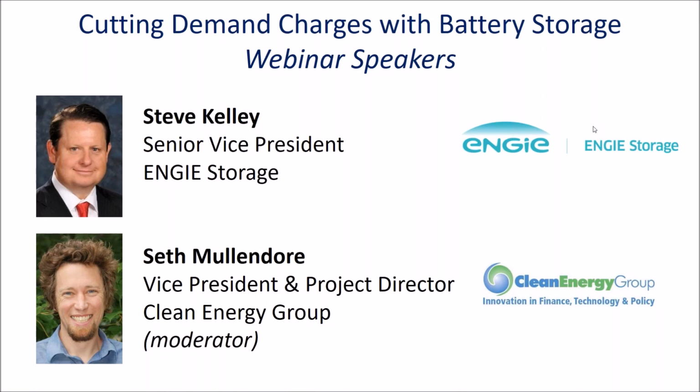Yeah, I think you'll see as jurisdictions and code catches up with technology, they are trying to figure out how to make this as safe as possible. And we have not had an incident or any concern with any issues with our energy storage system so far to date, but I think they're really trying to be protective around what are some of the critical things you'll need within indoor installations. And we've done a lot of indoor and outdoor installations. But what you're looking at now is the adoption of 2-hour firewalls within facilities, a maximum amount of electrolyte that you can install within an indoor structure.